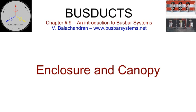Bus ducts with steel enclosure necessarily have to run an earth conductor of adequate size, supported from the enclosure, parallel to the phase conductors. Bus duct with aluminium enclosure need not be provided with an earth conductor, if the enclosure itself meets the minimum cross-sectional requirement for the envisaged earth fault current. Aluminium must be used as enclosure material for a current rating above 2000 amperes. Material of the canopy, installed in the outdoor sections of the bus duct, should preferably be fabricated from aluminium alloy.